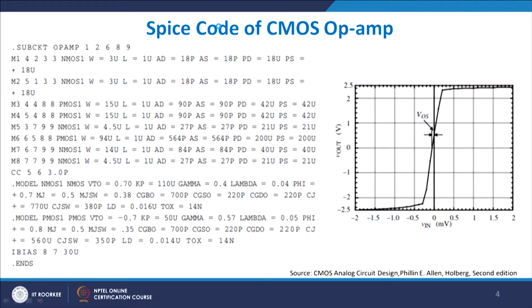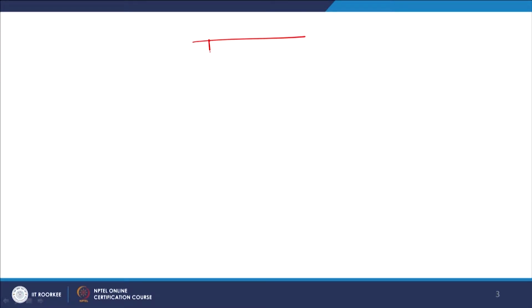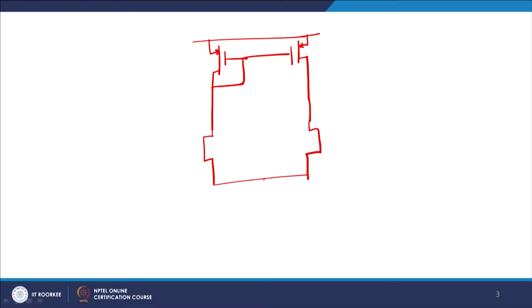As you can see, therefore, it will be something like this. This is again a PMOS and we are assuming a PMOS load, and this PMOS load is current mirrored here. Then we have one NMOS driver, another NMOS device here, and then we have this coming out like this. So, this is M1, M2, M3, M4 and M5, right.